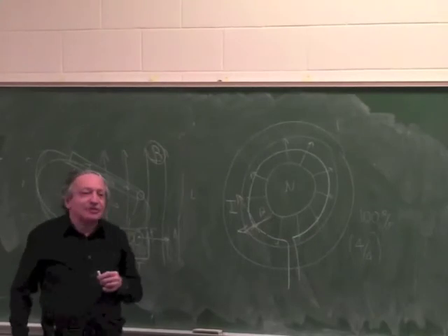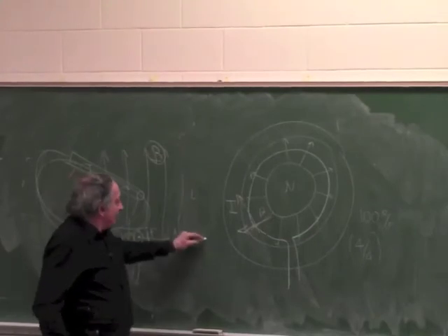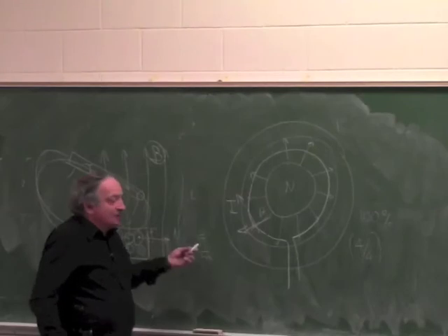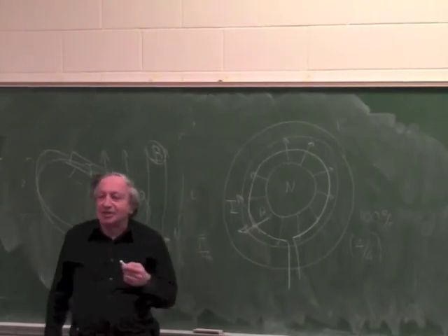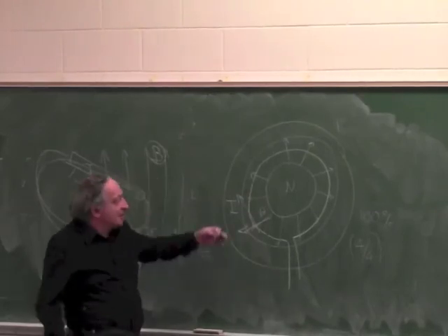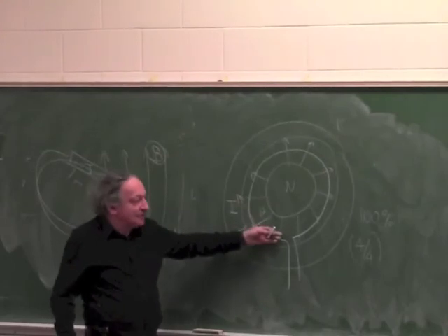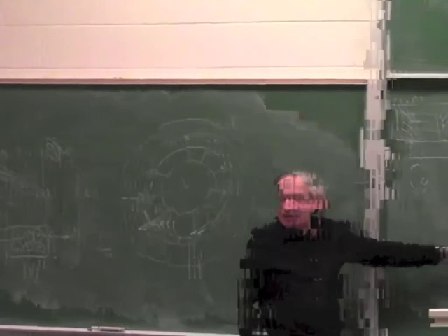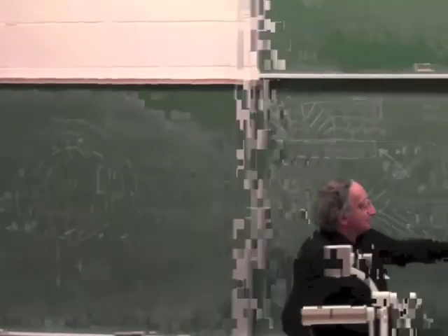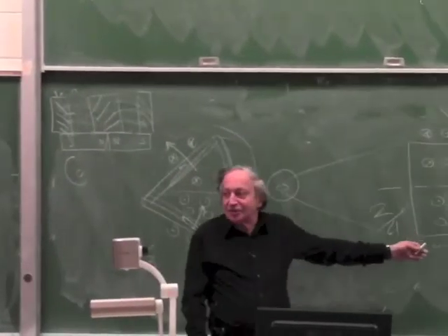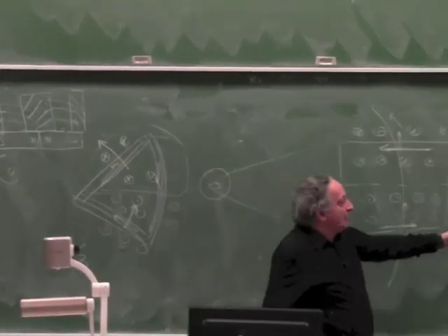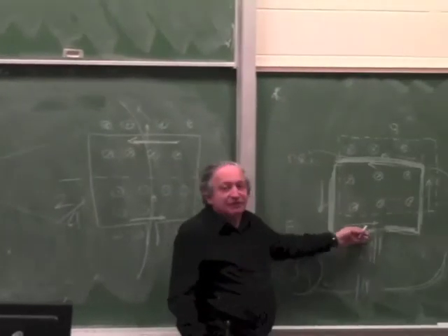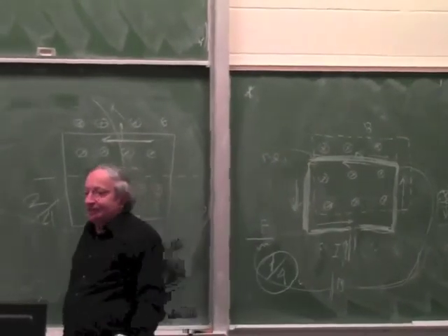But if we talk about F over m, the maximum force to mass, which determines acceleration, this is a 100% efficient actuator. Okay, disk drive is a 66% efficient actuator. Reversing the magnet is a 50% efficient actuator, and a plain loop in the field is a 25% efficient actuator.